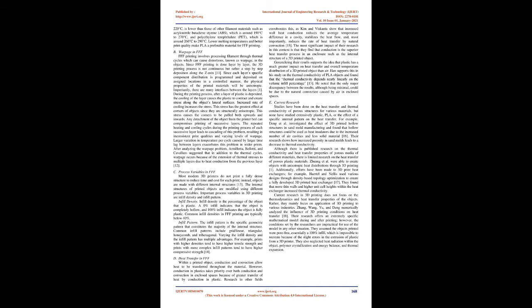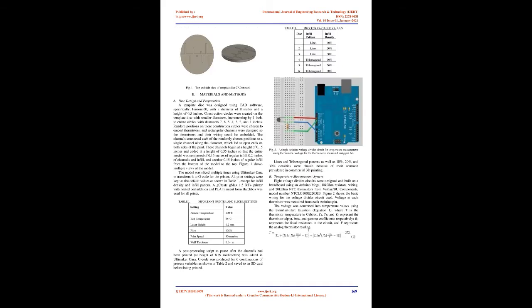Infill density. Infill density is the percentage of the object that is plastic. A 0% infill indicates that the object is completely hollow, and 100% infill indicates the object is fully plastic. Common infill densities in FFF printing are typically below 40%. Infill pattern. The infill pattern is the specific geometric pattern that constitutes the majority of the internal structure. Common infill patterns include grid/linear, triangular, honeycomb, and trihexagonal.